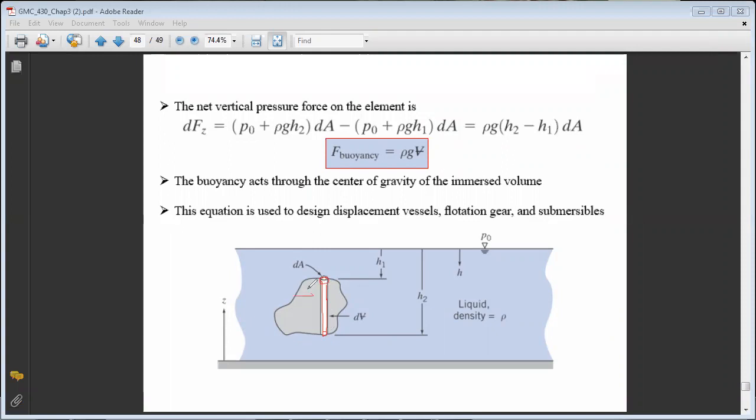So again, along the horizontal direction, effects will cancel out because we have seen that pressure forces of the liquid, which will be transmitted to this element, are equal in a horizontal plane. So no resultant force along the horizontal. I will just have vertical forces. Now, this element is subjected to which forces in the vertical direction? First, of course, its own weight, which is acting downward, so W.